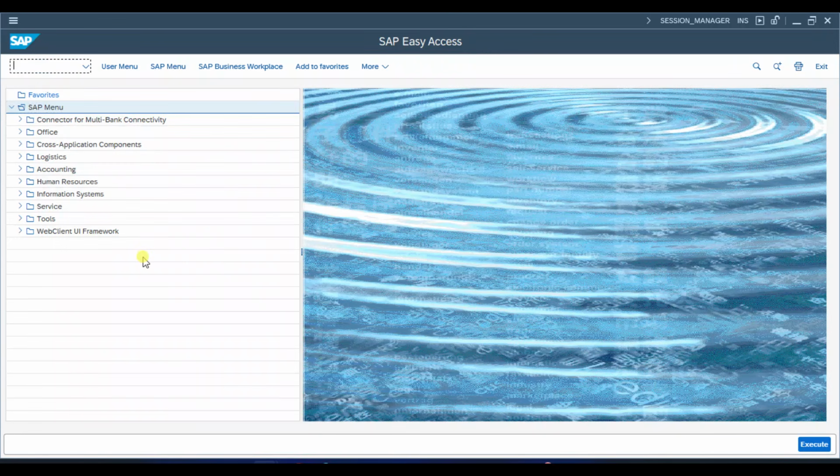So here the transactions that we basically use are CC01 to create a change master, CC02 to change it, and CC03 to display the change master. On the right side you can see the transaction mode of this particular screen. First I will walk you through the options that we have in the change master, and then we will proceed to create a change master and try to make some changes to a few of the master data objects such as the bill of material or the routing.